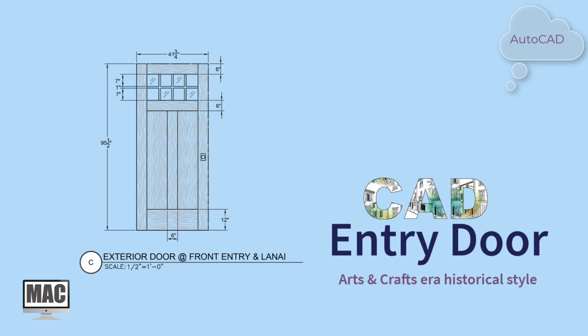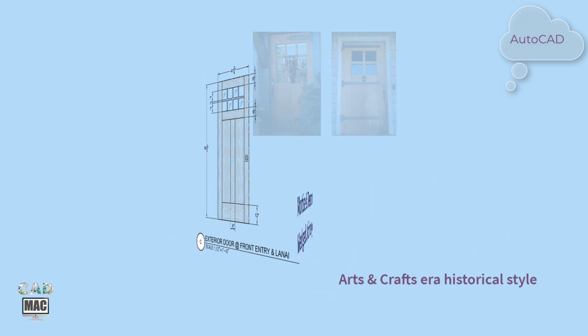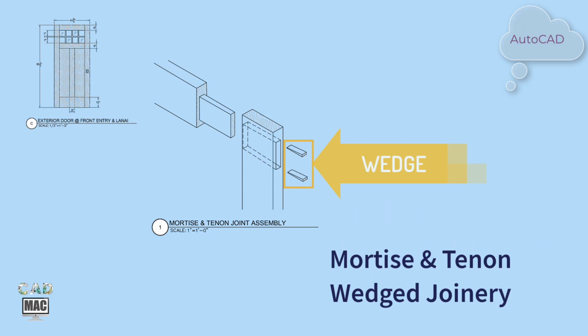In this video tutorial, we continue with the design of the Gatekeeper's Lodge doors, drawing inspiration from the arts and crafts historical era of architecture. Today we're drafting a typical entry-style door with mortise and tenon joinery, but in this instance, since the door is meant to be an entry door, the material should be thicker and the tenon will go through the mortise of the style and secured with wedges.